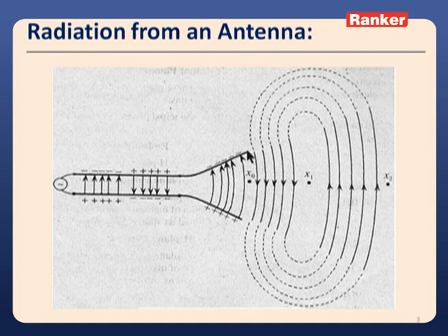So what it does is detach from the conducting medium and go into space as an electromagnetic wave. Clearly remember that up to this particular point, this is the voltage and current signal that we are considering for analysis. After this point x naught, the electromagnetic wave comes into the picture and goes out into free space, like a balloon or a simple smoke that you can imagine, just going out into free space. This is a simple radiation mechanism of an antenna.